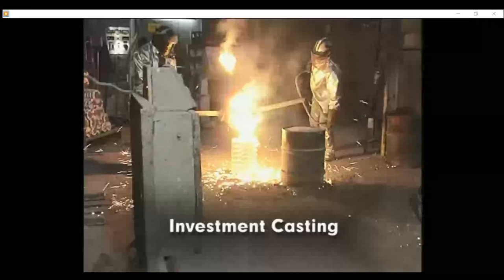and assemble it in a box here and put in sand, ordinary green sand. Then you bring two shells, one shell and one shell, and you cover here with the sand, ordinary green sand, and then you put the liquid inside. Finally you destroy this mold and it comes apart. Let me show you another video to make this one clear.